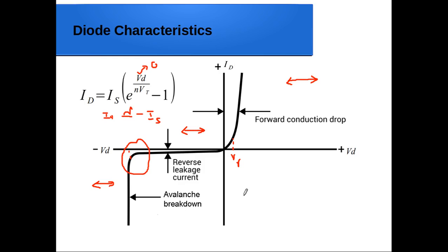This happens because of the phenomenon of breakdown. Breakdown can happen in a diode in two forms: avalanche breakdown and Zener breakdown. Whatever is the breakdown occurring, if the diode breakdown occurs for a fixed voltage, then such diodes that operate under such conditions are known as Zener diodes. Zener diodes, due to this particular property, are applicable in applications such as voltage regulators. But our ordinary diodes, which are commonly known as signal diodes, if used under such conditions, will break down completely and they get damaged. We cannot use them anymore.